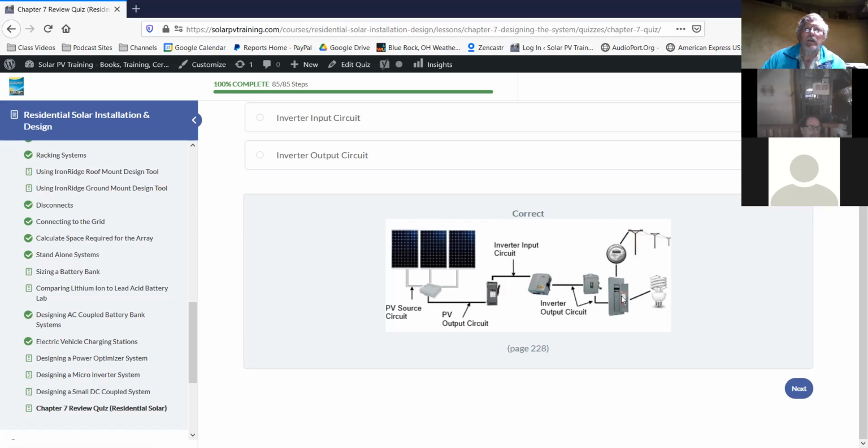Right. Okay. And so then the question, I guess I'm also thinking through why. The reason why we're putting the inverter disconnect on the load side of the inverter is because that could be a battery system that even without the panels, you'd be generating electricity. So you want to kill it from the load side of the inverter regardless. Right. I think it is a bit of a legacy thing because in the olden days, before the inverters had the anti-islanding provision, the code said you've got to turn them off.